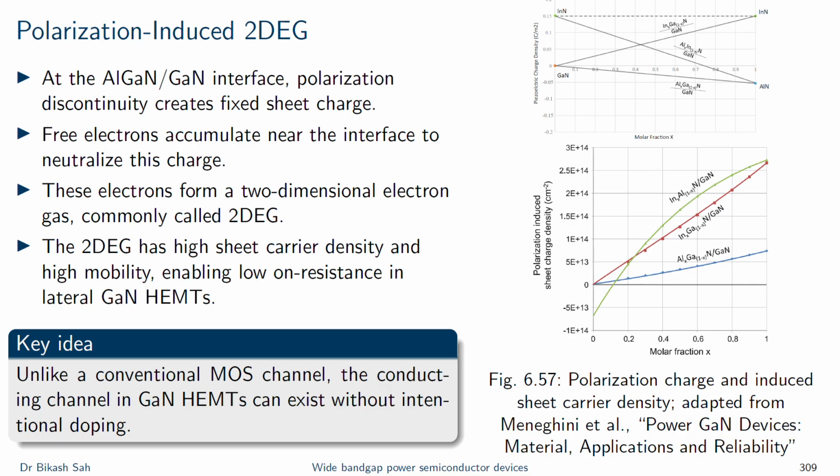For me, the teaching point is that this conducting path is not created in the same way that we were learning in silicon, which was because of the inversion channel or the accumulation channel, right? So in a MOSFET, we apply gate voltage to induce an inversion channel, but in a GaN HEMT, the 2DEG may already exist because of the polarization and the heterostructure.